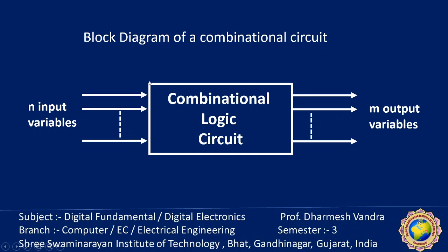In many applications, the sources and destinations are storage registers located either in the vicinity of the combinational circuit or in a remote external device. But as per the definition, the external register does not influence the behavior of the combinational circuit, because if it does, the total processing becomes sequential.